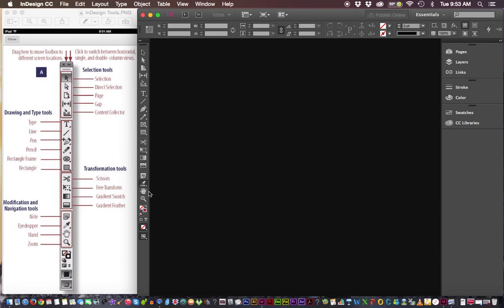But the hand tool is useful, though instead of clicking that tool, I usually use the Spacebar key. Temporarily, when I'm using any tool, I can hold down the Spacebar, except if I'm in the text tool, and then we can navigate the system.